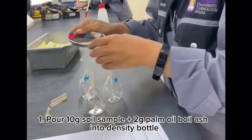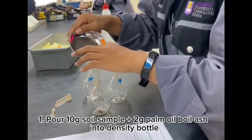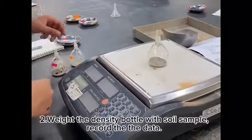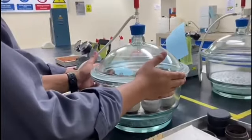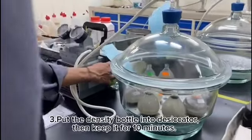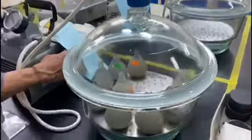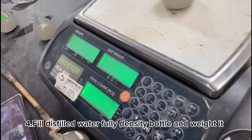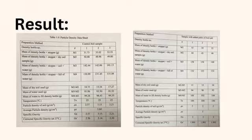Pour 10 gram soil sample plus 2 gram palm oil boiler ash into the density bottle. Weigh the density bottle with the soil sample. Third, put the density bottle into a desiccator. Then keep it for 10 minutes. Fill the density bottle fully with distilled water and weigh it. This is the result that I got from this experiment.